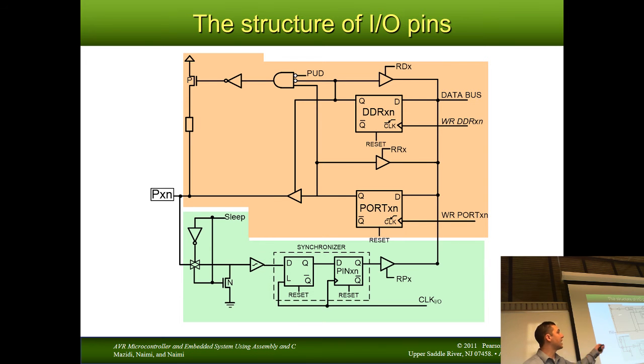This is the basic setup. We got a DDR register, a port register, and a pin register, and that's how they all work together to form those 5 states I just talked about. Well, not really. It talks about 4 of those states. To get that 5th state, that toggle state, we have to go right to the data sheet for the 328P.